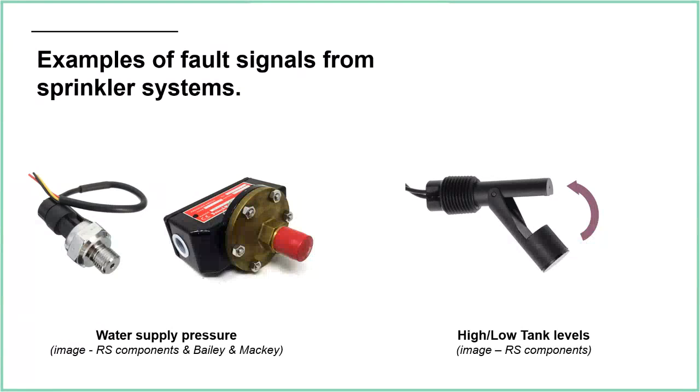Another thing we need to monitor is the water in the tank, the liquid levels. That's often done with one of these style of sensors. So it's just a simple float. So when the water level rises, it's going to close that sensor. So that one is, I guess, normally open. So that's probably your high alarm. So when the water level goes up to high, it's going to close that circuit and send you an alarm.